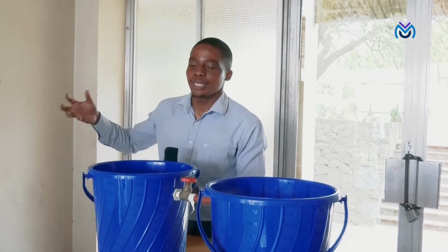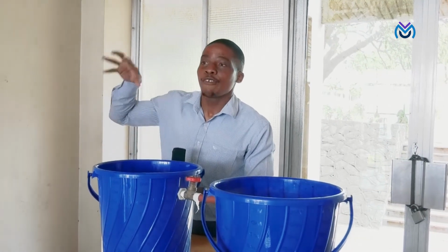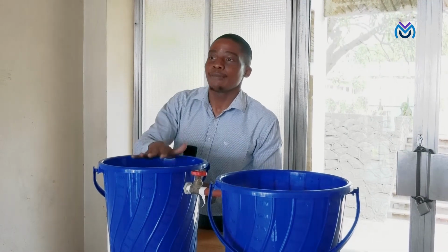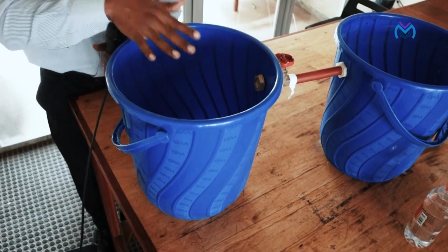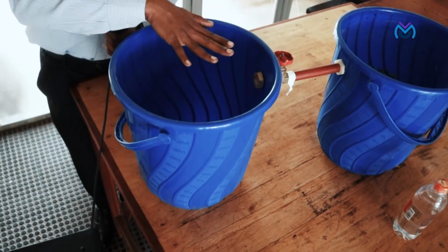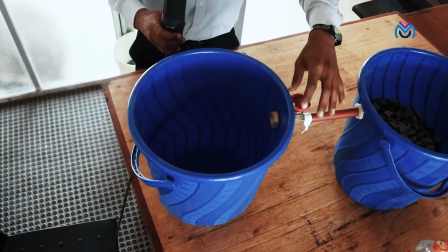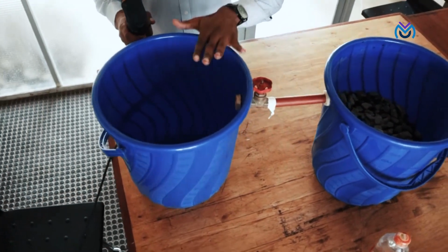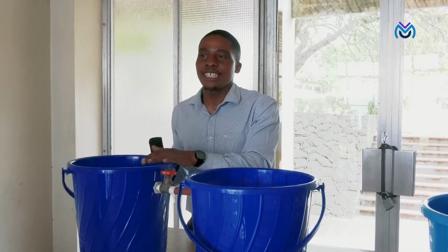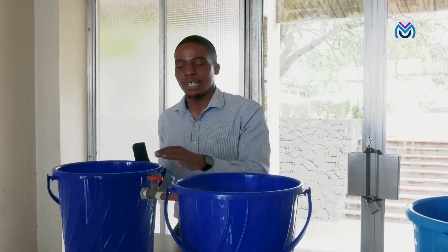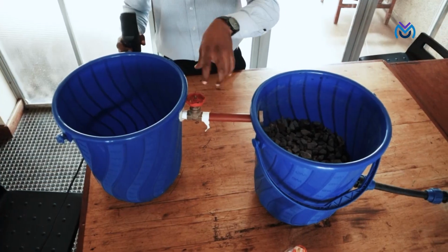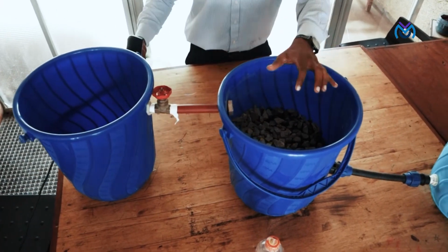So as the wastewater is generated from the factory of the brewery, it enters this sedimentation tank. As this sedimentation tank is full, we'll open this valve after a certain period. Let's say a detention time of 1 hour. As we detain this water, we'll open the valve. Once we open the valve, the water will enter the filtration unit.